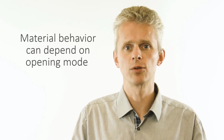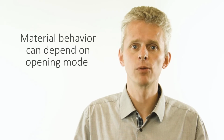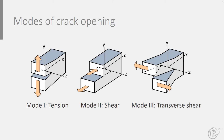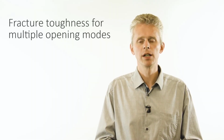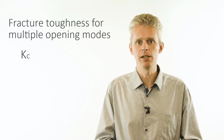Because the resistance to cracking depends on the opening mode, one generally has to specify for which opening mode specifically a parameter is quantified. For example, the fracture toughness is generally defined as the resistance to fracture of a crack in opening mode 1, hence the notation K1C. In case a crack reaches a critical length with a combination of opening modes, then one should refer to the critical K with only the subscript C.